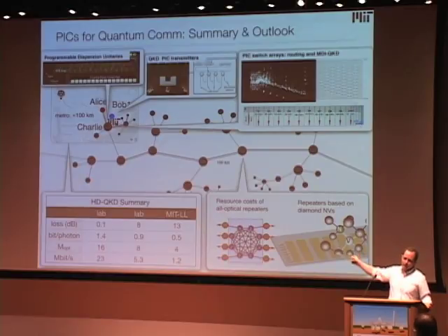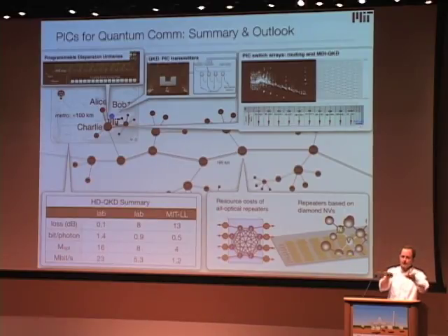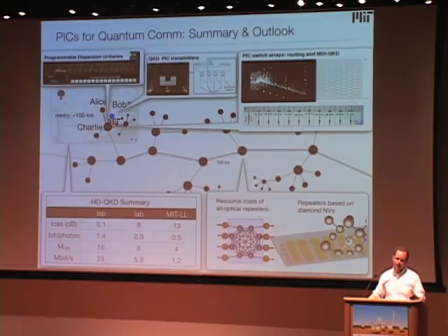The switch arrays that I've shown actually use thermo-optic modulators that operate at about a microsecond switching time. So considerably slower. But in a network application, oftentimes it's fine, right? If you just want to allocate modes to different users. A microsecond, but the benefit of that is the thermo-optic modulator is essentially lossless. So we see basically zero loss with one of these modulators.